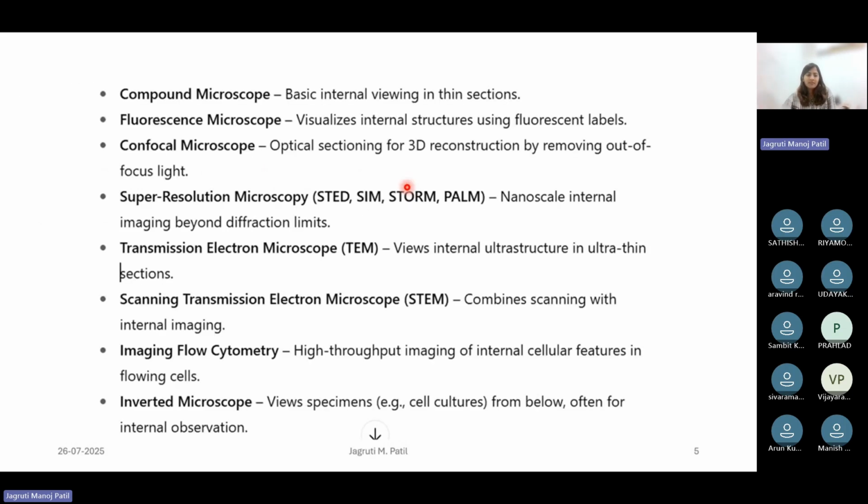Okay. This was holistically what we talked about in the previous slide, using the images you saw. TEM will give you an internal ultrastructure through TEM slices, but the sample you need to make for TEM is very small, hardly more than 3 or 4 mm at maximum. Also, TEM is mostly an expensive instrument, so you need specific requirements. You need a grid in which you place your sample, you need to process your sample, and the instrument software and data acquisition are also a lengthy process. Hence, people usually go through SEM first for microscopy.